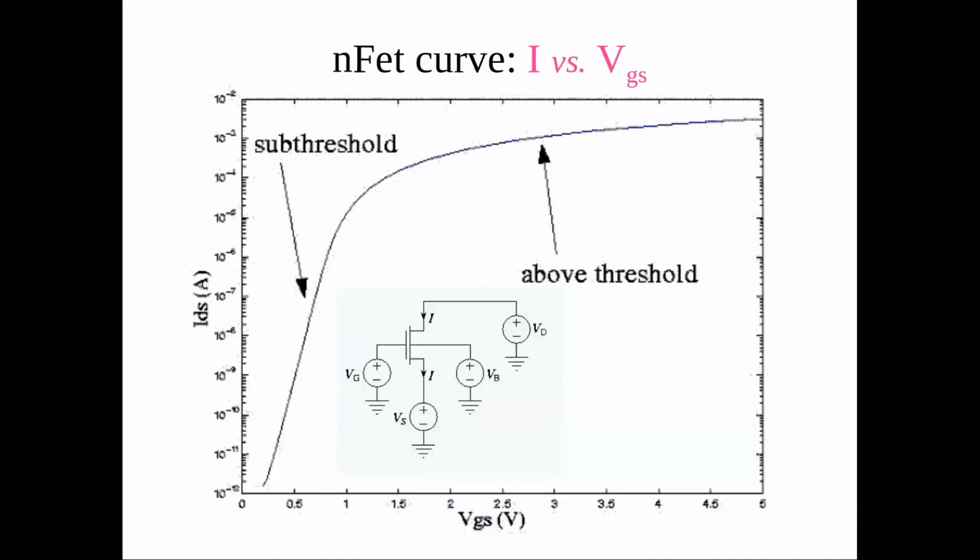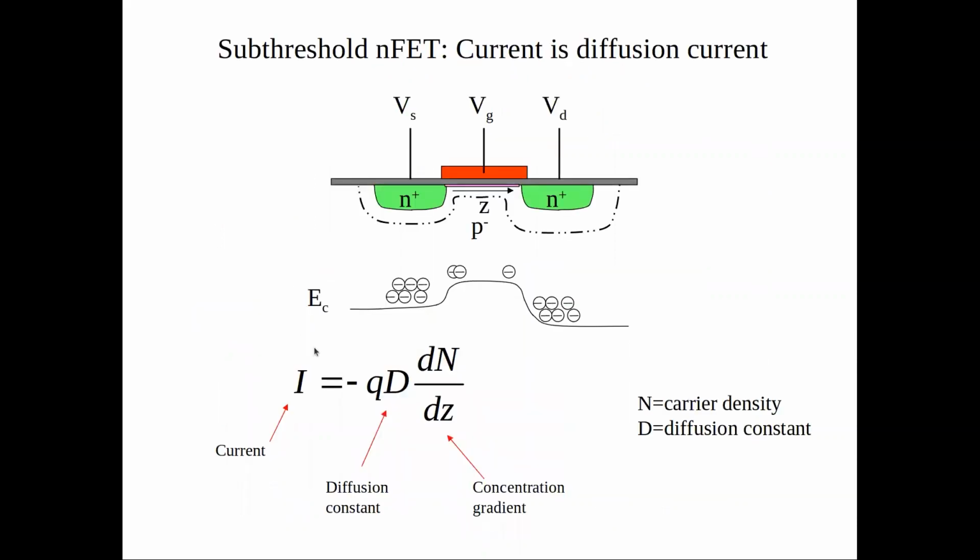But anyways, going back to MOSFETs, we're going to be doing circuits next week that use this relationship. And we're going to mainly see how to do circuits that exploit this relationship. And again, to remind you what you just asked, the current is because of diffusion, and the basic relationship is this Einstein constant with the difference of concentrations.